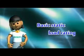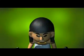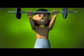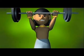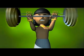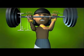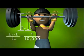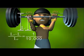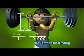Basic static load rating. Let's illustrate this with a simple example. Suppose an athlete at a weightlifting competition gradually increases the weight on his barbell. The more the weight increases, the more the weightlifter's arms flex. If the length of the person's uplifted arms is L0 and the length of his arms after lifting the barbell is L, when L0 minus L equals 1/10,000th, we call the weight the basic static load rating.